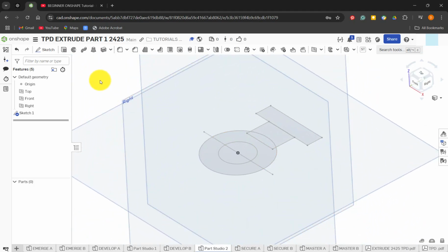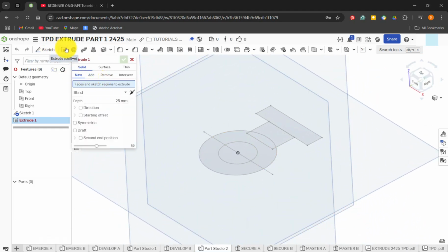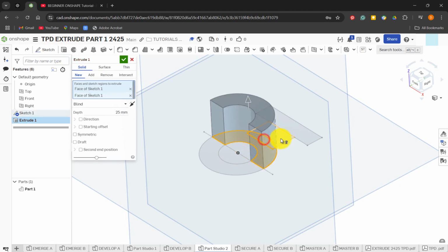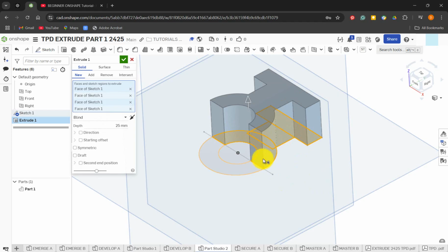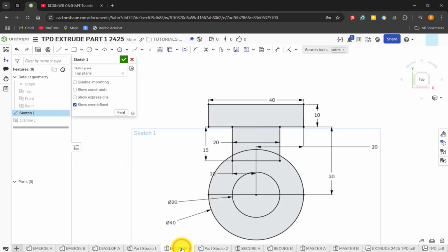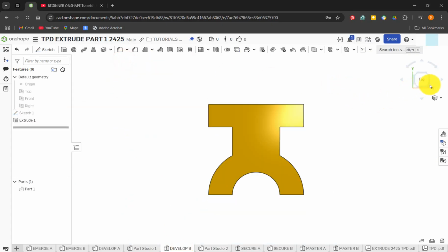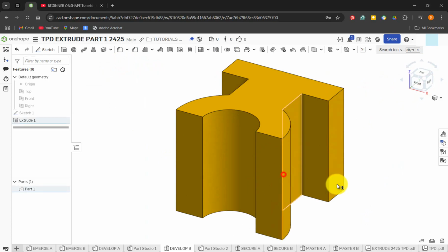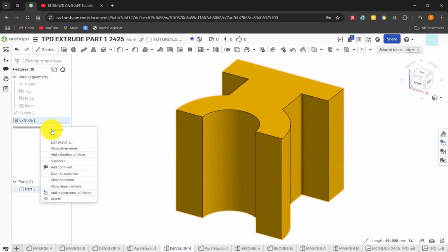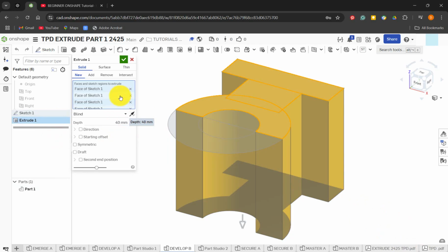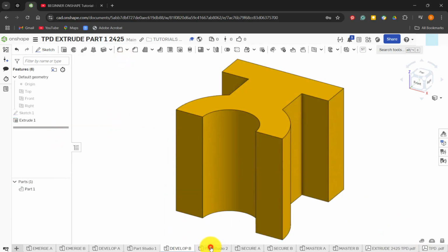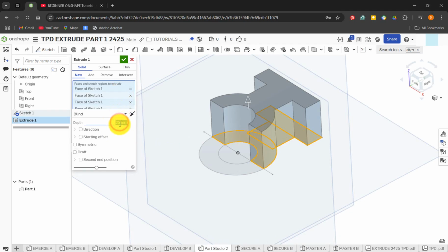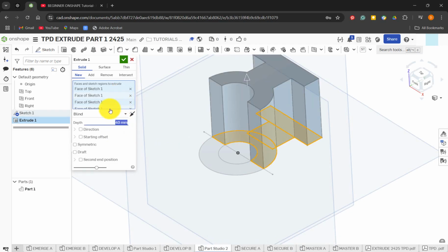You can see that line now. It's going to go Shift and E for extrude, and this time it'll allow me to select just part of that curve. Okay, and you can see I've got the shape I wanted. So I'll go back to here, and I'm going to check the size. There's two ways of doing that, as we've seen before. We could just select one of these edges, it tells me it's 40mm, or I could go into there and you can see 40mm. And that is it. So I'm going to type in 40, and I'm going to confirm that, and it's a new part, so you can see here it's going to appear, and we're going to click tick.